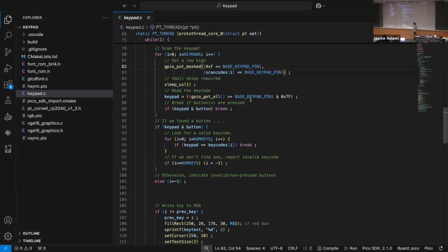And you will notice, many of you already have, that when you hook it up and you just start running it without pushing buttons, it's just streaming out -1s. Here's where the -1 is being set. This is just no valid key code. As soon as you push a key, it will print out the value of the key that's been pressed. The way that it knows the value of the key is that is as far as it got in this for loop through each key looking for valid key codes. I got to index 5 and I found a match. Button 5 was pressed.